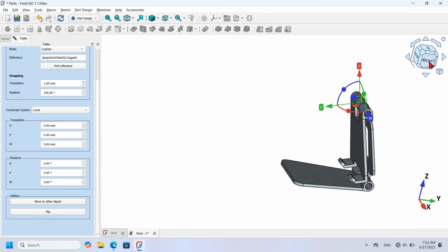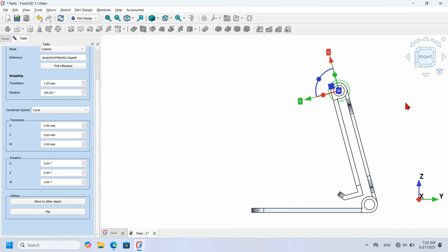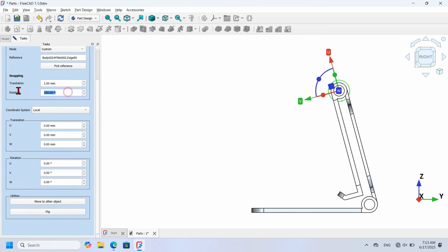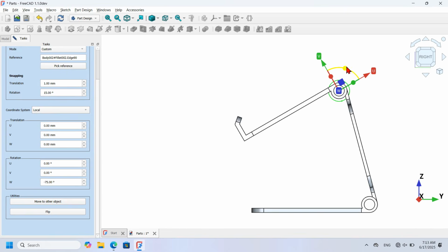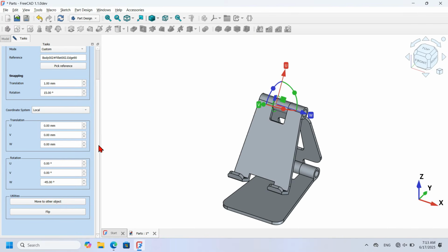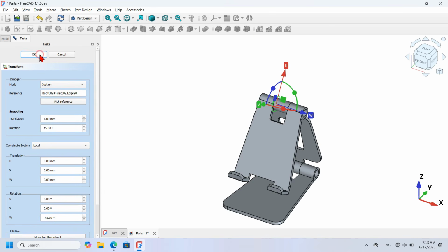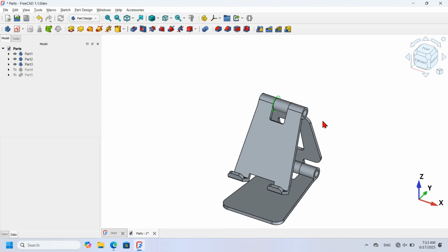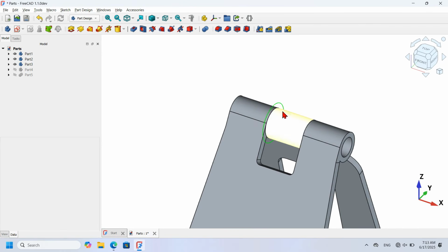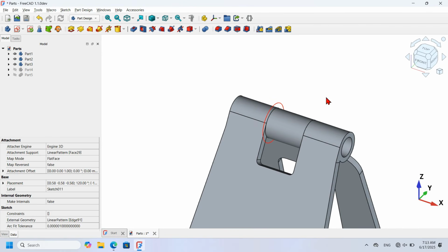Now let's change to right view and let's rotate this 3D model. For that, first let's change the rotation increment to 15 degrees and drag this point. As you can see, I have this. Now I press Home on the keyboard and I scroll up here and then I press OK. Now I will hide this sketch here. For that, I will select this geometry and press spacebar.